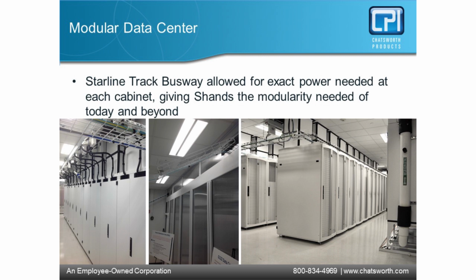If I look at the other aspect of cold aisle versus hot aisle, whenever I create a cold aisle containment, I'm creating a box, in essence, in front of those cabinets. And that box has a specific amount of air capacity to it. If I have the slightest hiccup in my air system, or if I all of a sudden see a peak, I could actually undersupply the amount of air needed and overheat devices. So the challenge with cold aisle containment is that it has that limit.